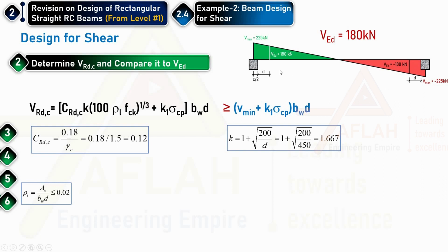So after some dimension, the reinforcement that was extended from the midspan may not continue. This is a possibility. Mostly we may provide it for simplicity from one end to the other side. However, some engineers, to be economical, may cut some of the reinforcement or may bend it upward and do it at the top.